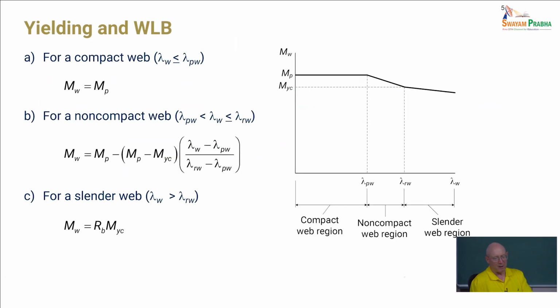So the way the calculation of that plateau strength works, and if you've got a compact web, so in AISC, a compact web, and I'm going to refer to Eurocode a lot, knowing that the Indian standard is largely very close to Eurocode. So I'll mostly just make comments back to Eurocode here. If we have a compact web, that is basically class 2 in Eurocode. So we're looking to be able to develop the plastic moment resistance. There are other limits that would be equivalent to Class 1, but the main specification provisions are just focused on calculating strength.